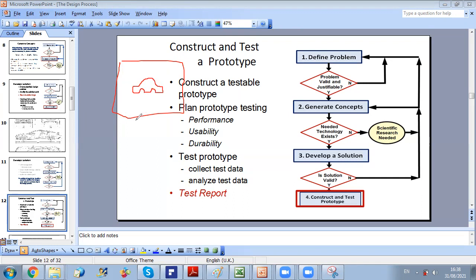If you remember from fluids, the condition is to have the same dimensionless numbers. So we have the same Reynolds number, let's say. We study the problem and consider what dimensionless groups are involved, let's say the Reynolds number, the Mach number, etc. And we determine what the geometrical parameters of this car should be in order to satisfy similarity, and not only the geometrical parameters. Let's say you are doing a wind tunnel experiment or test on your prototype. You have air flowing at a certain velocity v. You can even use a different fluid.